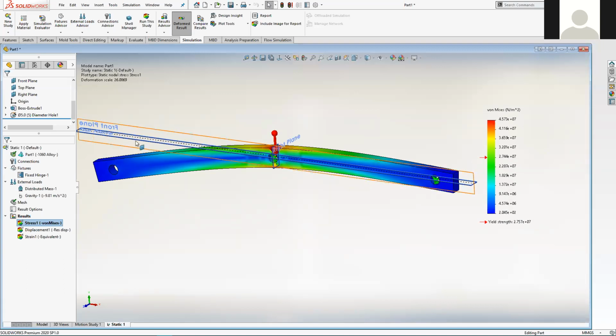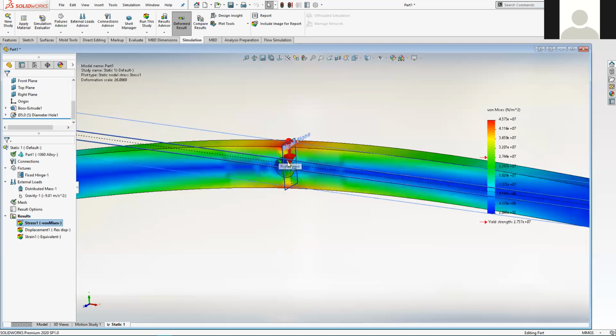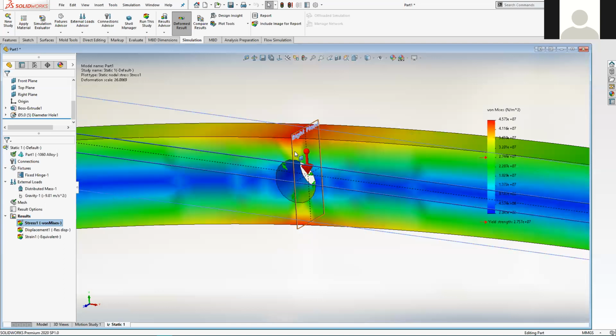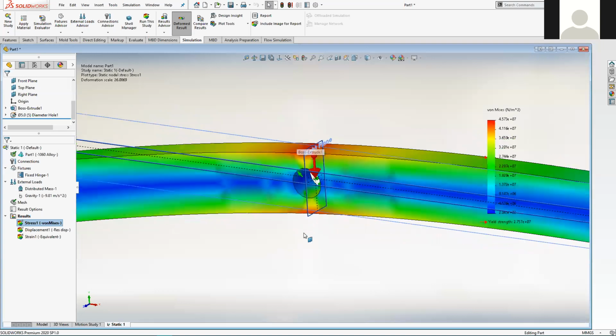If you do that over and over again, it's going to fatigue pretty quickly. That spot is going to work harden, and then arguably it's going to split, and then it's going to be a cascade effect, and eventually it's going to snap through, probably above this hole. So yeah, that's never good.